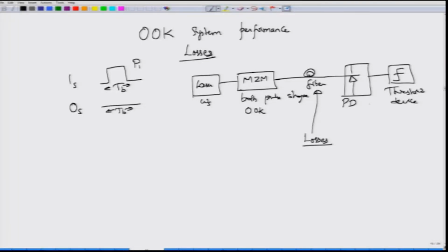The second thing that can go wrong is that in the photodetector and the optical receiver circuit, you find noises. What kind of noises do you find? Well, we have already seen the shot noise, which operates in a circuit such as a transimpedance amplifier when the optical power is sufficiently large, such that the shot noise can dominate over the thermal noise, and that is where you would like to operate the system. So, shot noise dominating thermal noise when the optical bit corresponds to symbol 1 is a typical condition.